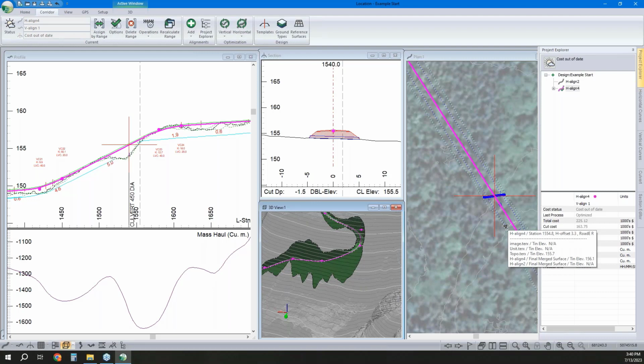Separate alignments are separate and treated as such, but they can be displayed in the plan view and cross-section view of the current alignment and plan profile view. But to get the cross-sections along that independent off-take ditch, you're looking to do that as a separate one.